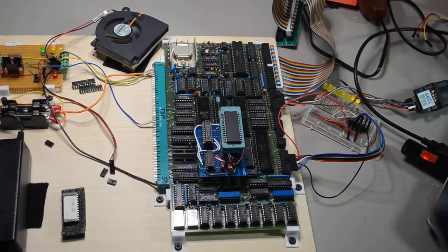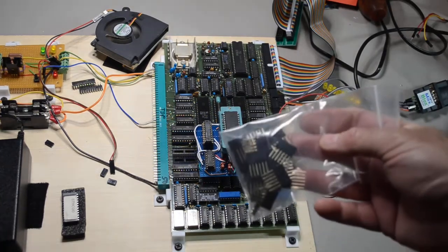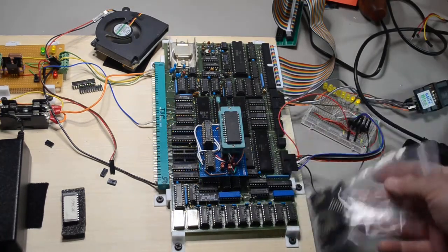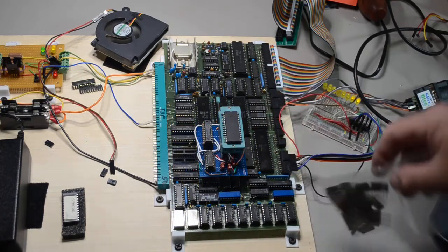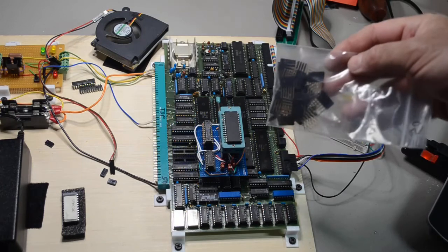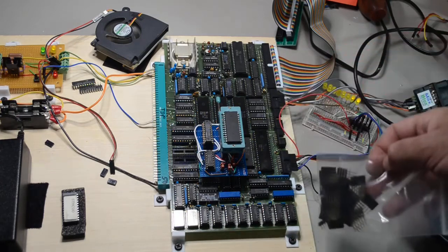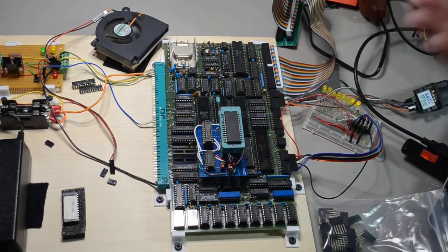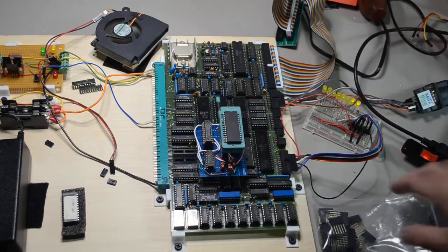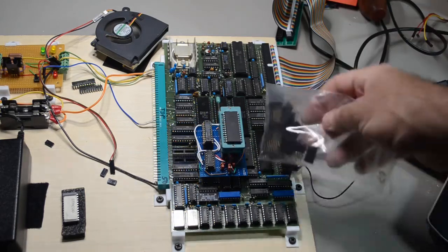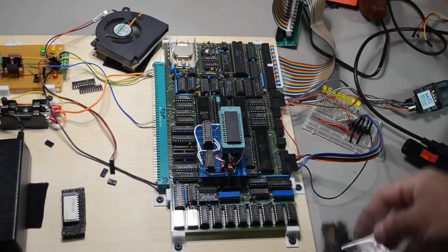I made the mistake of thinking that these headers, which I'm using to hold the board up, are like Arduino headers. You know, that they're great because you can plug them into each other and you can stack boards, which is what I wanted to do to build the daughter board. I wanted to stack one board on top of another board. So I had these plugging into the IC sockets.